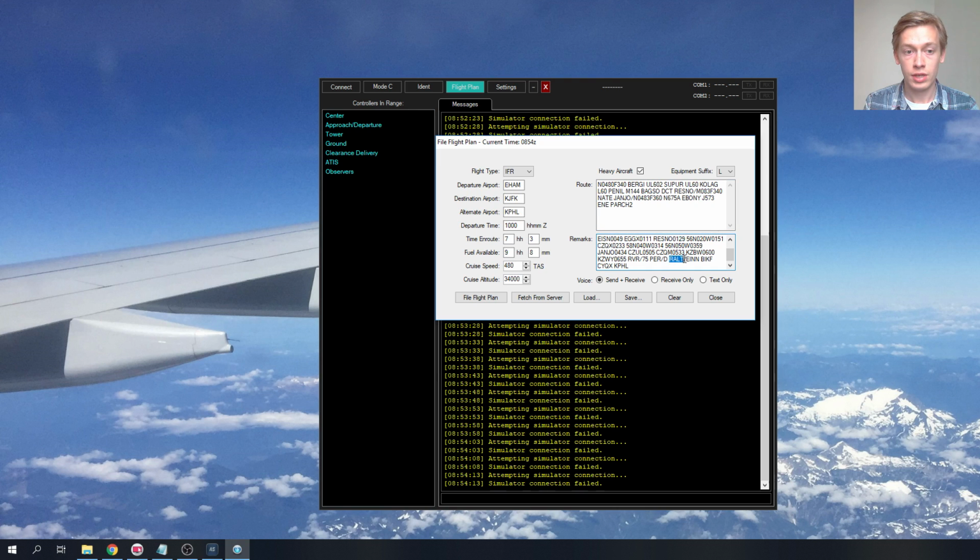Maybe worth mentioning here, you can see the en route alternates. So ATC knows what our en route alternates are. For example, Shannon, Keflavik, Gander, and Philadelphia are our en route alternates. Okay, so if this is all correct, especially if the Mach number and flight level at the Oceanic entry point is correct, you can file your flight plan to VATSIM.